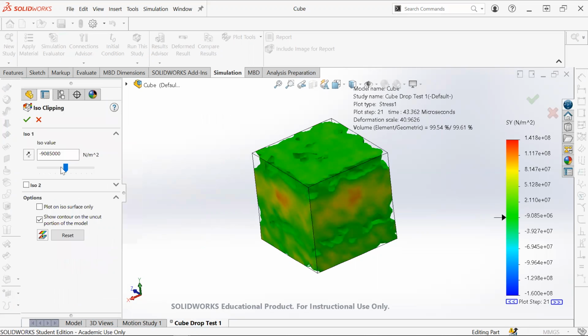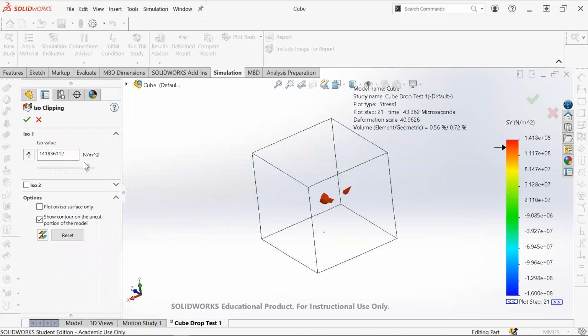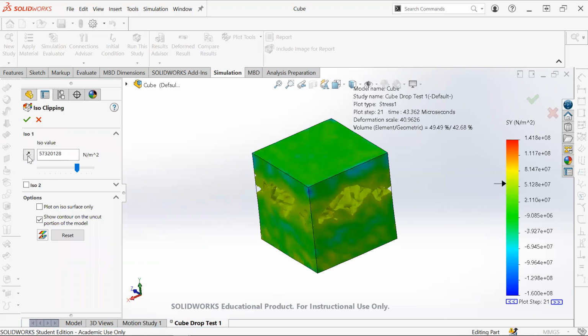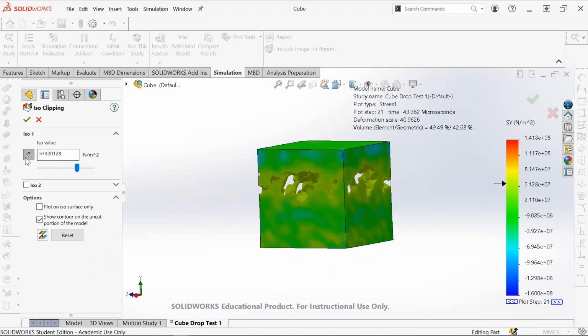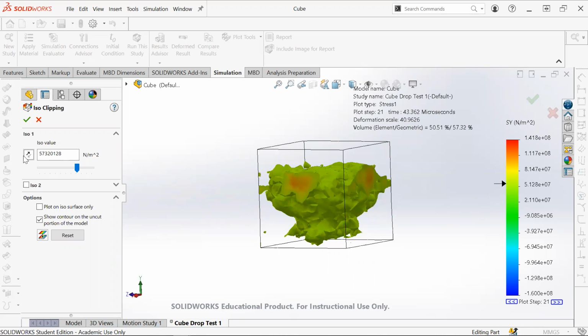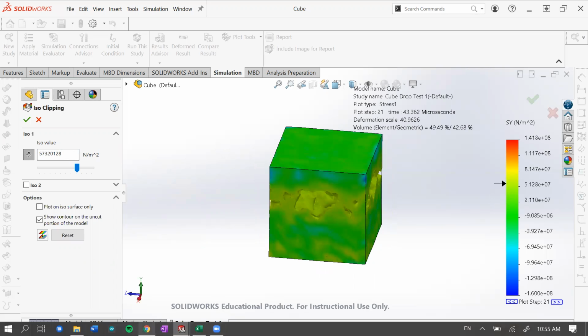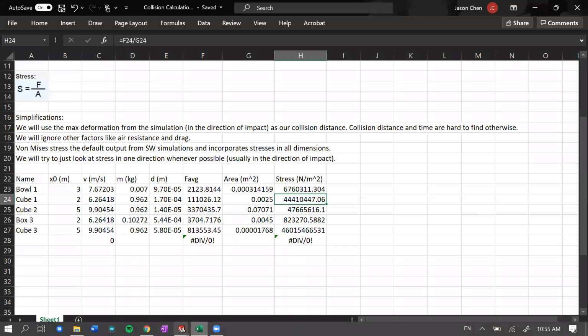Basically what this is, it's very cool. You can choose a cutoff, right? A cutoff point for the SolidWorks simulation environment to choose all the sections that are either above or below the cutoff point. To choose above or below, you hit this button here. As you can see, it's like the inverse. These are all, I think, above this number here, and these are all below this number here. It's another part of the validation process, honestly.